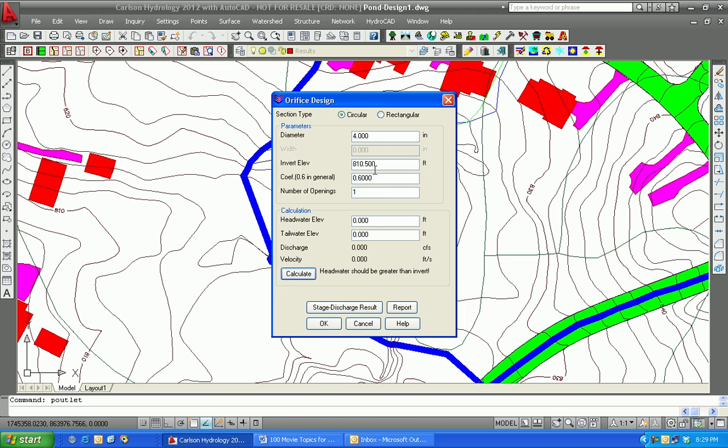Oh, and the headwater condition, I should point out, is 815. That's the top of the pond. And this little guy produces less than 1 CFS coming out of it, but it'll drain sort of the baseline flow. That's one little option.